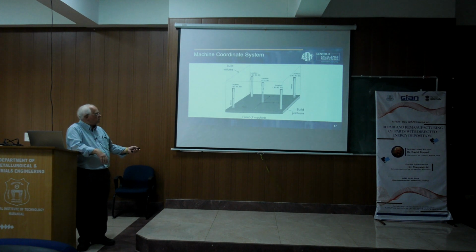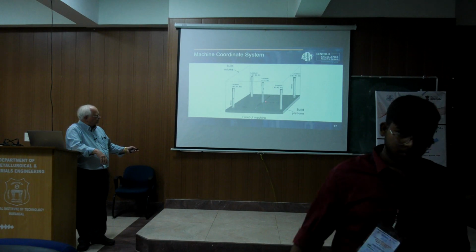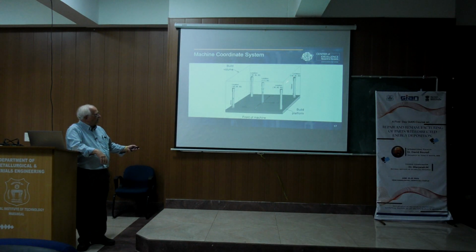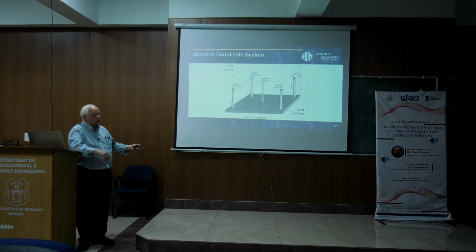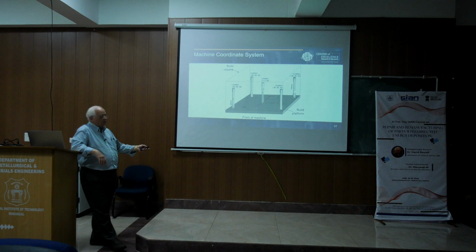This is for a part with a 180, maybe 200 millimeter square build form. So this part would be in a positive x direction of about 90 millimeters, a positive y direction of about 90 millimeters. And if this part is 100 millimeters across, the center of it would be at 50. So we would have this coordinate 90, 90, 50 for the location of this part.